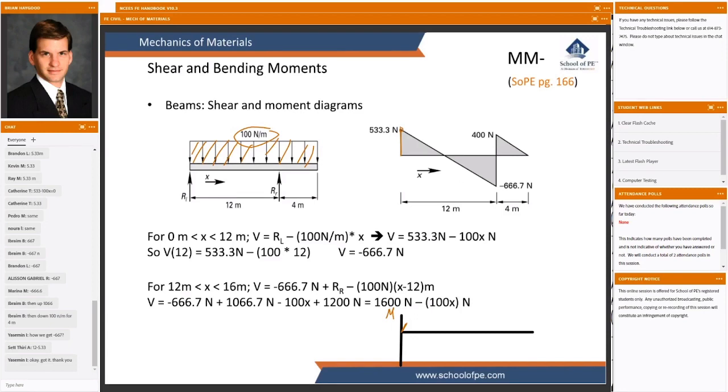It certainly seems like nobody's trying to twist the end of this beam off, so I'm pretty safe to start at a moment value of 0. Similarly, I don't think anyone's twisting the right-hand end of that beam off, so I think we're going to end up at a moment value of 0 as well. So again, you could start from the left or start from the right. Either one would work. If this beam were cantilevered off of an anchor on the left, then we might have an applied moment at the side, and that would start us off with some non-zero value on our moment diagram.